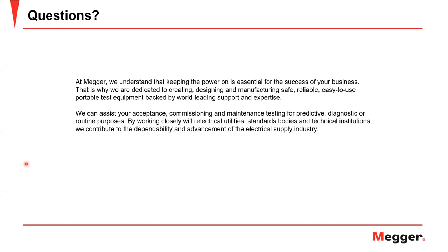All right. So Sugosh, next question's for you. Do you need a recloser system, or can the 79 element in a relay and breaker accomplish the same requirement? Yes, it is possible. In this setup, the breaker itself will be performing the tripping and reclosing action based on the currents that it is seeing in the circuit, and then the relay settings also for the 79 element. So the 79 logic in the relay will be monitoring the action of the breaker.